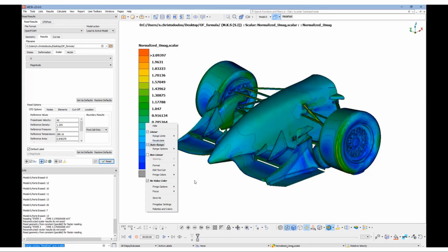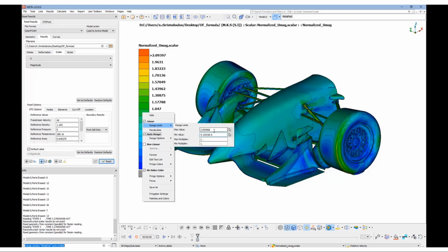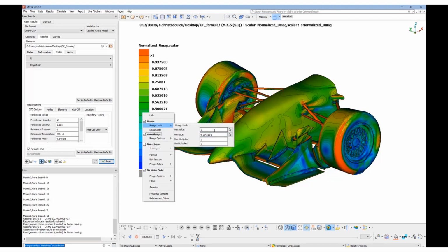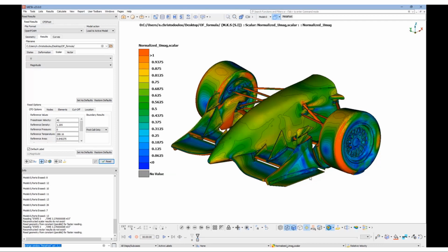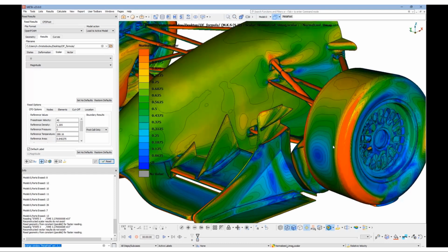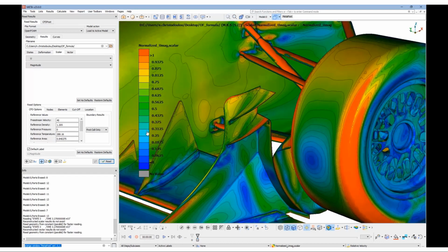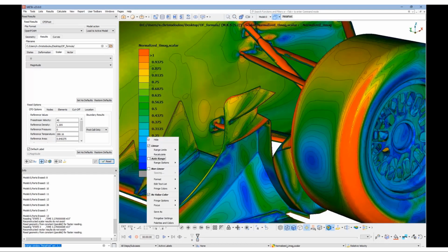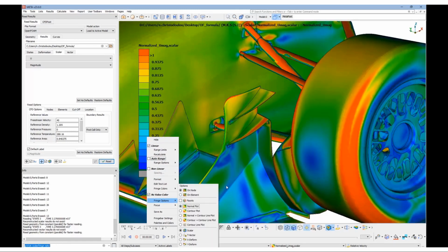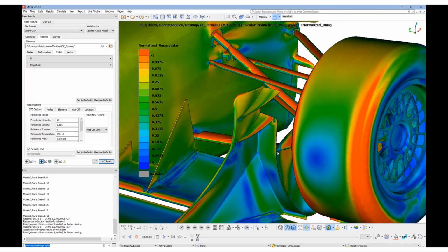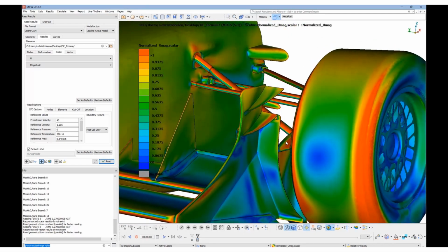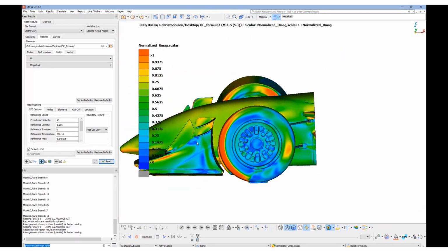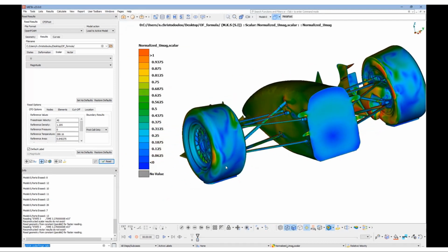We can see it also selected at the scalar selection bar below. And if we give the proper values now, like 1 and 0, we can see the proper coloring. Let's switch back now to the normal plot visualization. This is a nice contour plot since it shows clearly where we have acceleration of the flow.